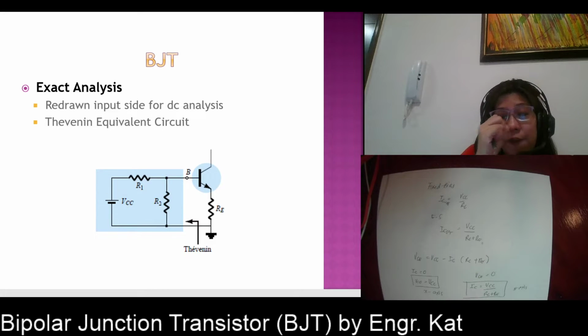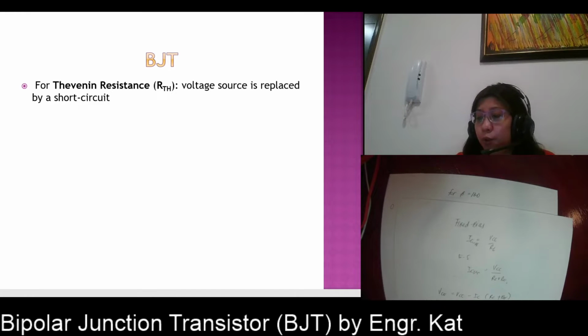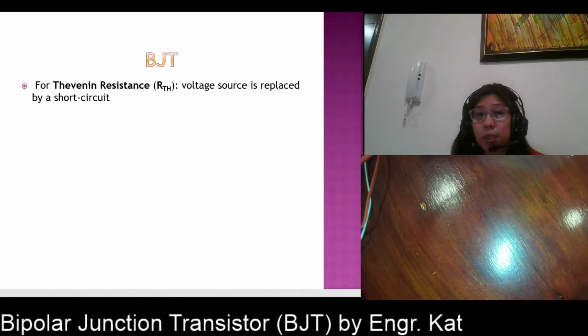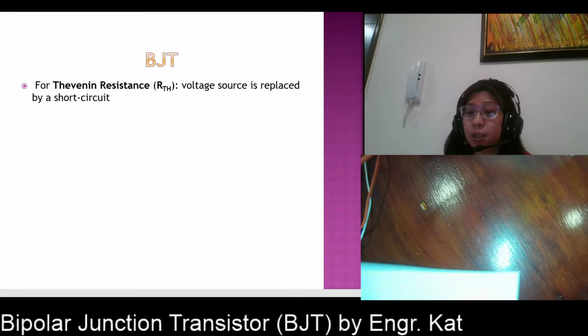So how do you Theveninize that? We are going to convert this into a single voltage source in series with a single resistance. So the first thing that you're going to do is solve for the RTH. So what is your RTH? RTH is your Thevenin's resistance.